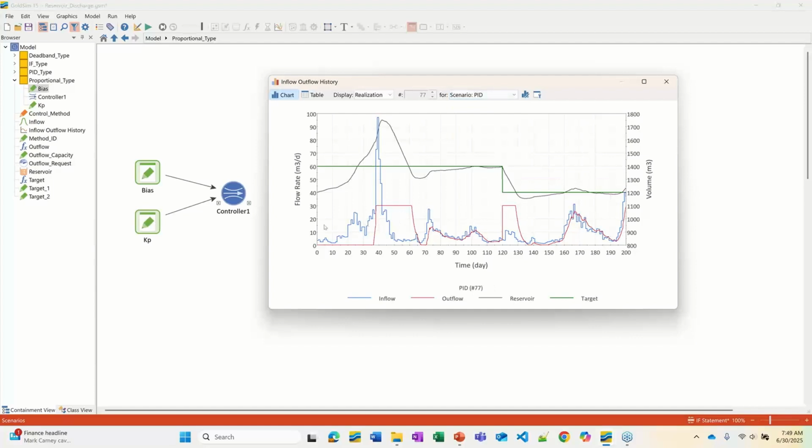With a PID, what you see here is that there's a big impact of the time factor now. You could call these overreactions. We have this big jump right here, and that all started with the problem of being too low for too long. We were so low for so long that it caused a big negative reaction, which caused us to delay a response, meaning we wanted to make up for this big error by rising above the target.